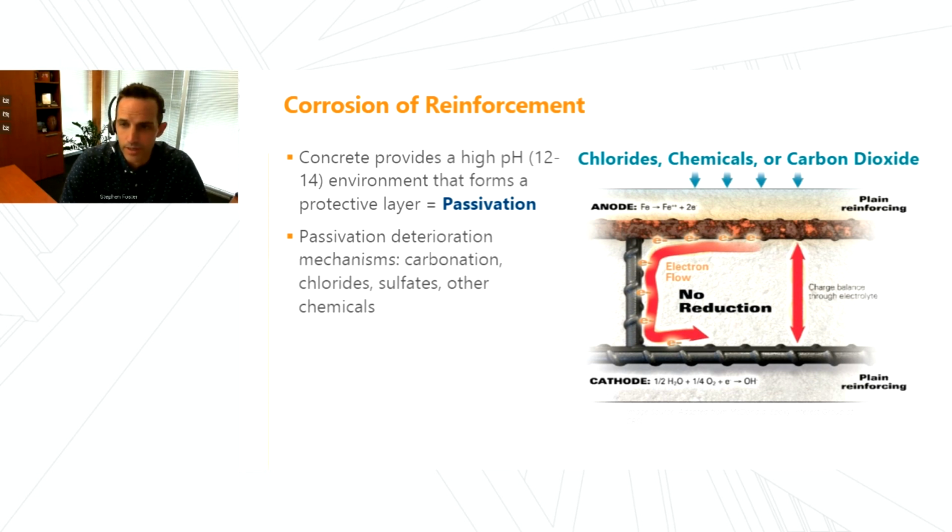And so the thing to remember here, and Terry touched on this a little bit with the concrete materials piece, right? It is strong, it's a durable material, but I want you to remember, basically your concrete is a sponge. I mean, it's a big, hard, strong gray sponge. There's air in there. There's a pathway for these types of chemicals to permeate, sometimes at the molecular level, right? It's not as porous as a sponge is, obviously, or wouldn't retain the water. But chemically, you can think of it that way. And right, so that allows for some of these products and materials to penetrate over time.